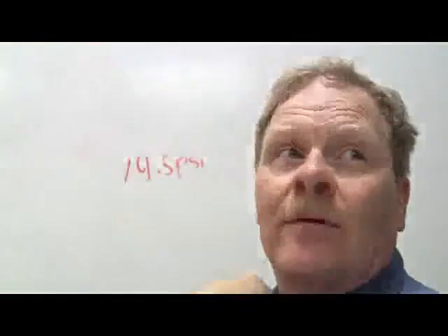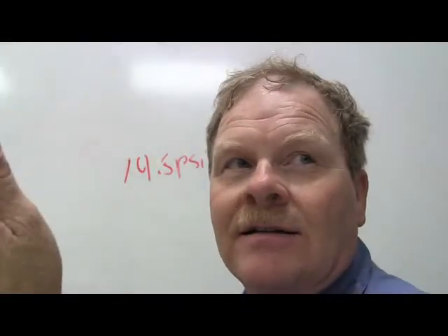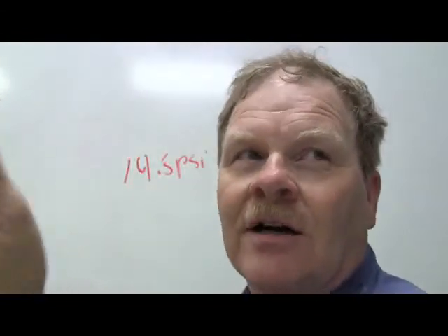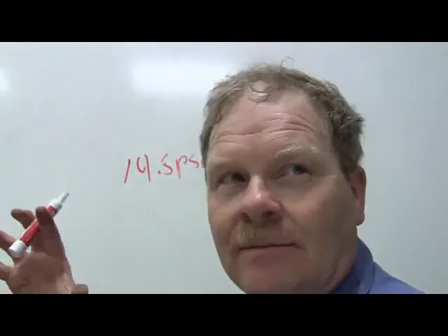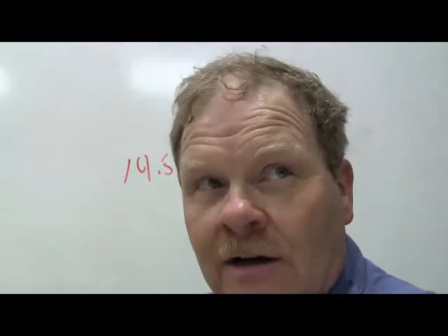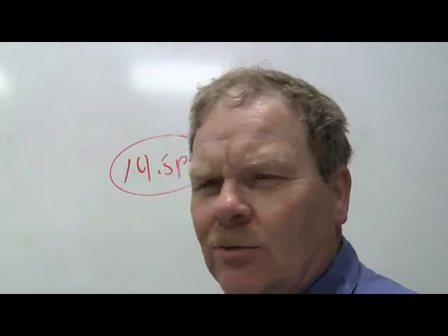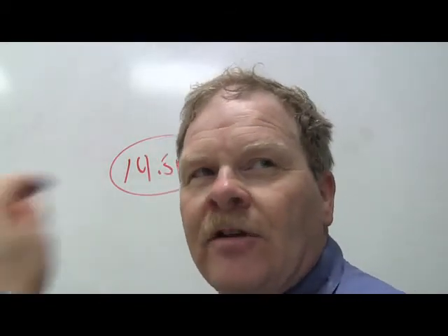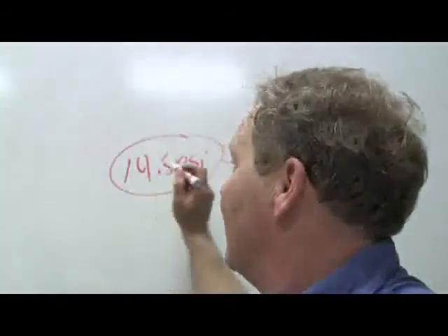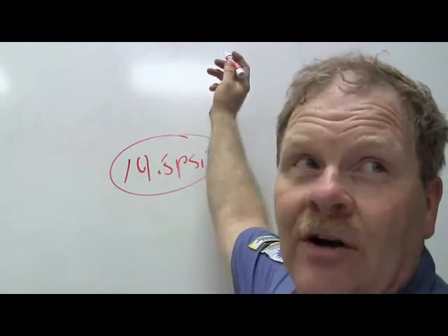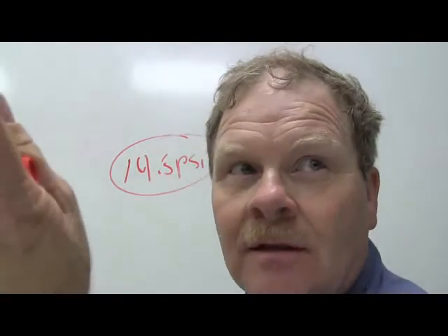Okay, so right now, from our perspective, the pressure we're sitting in is 0 pressure. It's really not, but it's our starting point because that's where things are when nothing is being either pulled out or shoved in for pressure. Well, it's about 14.5 if we're at sea level, right? That's why they say about 15. So if you're adding psi-G, the absolute pressure is going to be about 15 plus whatever you're adding. That makes sense? You get what I'm saying?